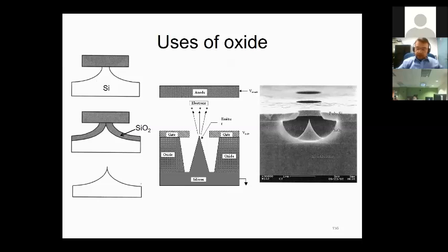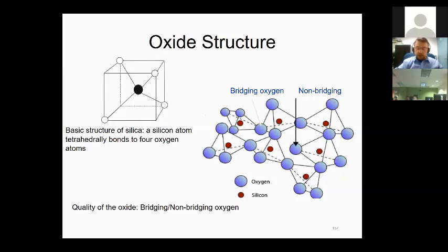All right, the thing that I want to emphasize is, since silicon dioxide is a native oxide of silicon, it will actually consume the silicon while we're growing it. So you see, if you have this kind of formation, and you grow the silicon dioxide on top, while you're growing the silicon dioxide, you're consuming the silicon underneath, so it doesn't stay at the same level. That's very critical, and we should never forget that we're consuming the silicon in the first place.